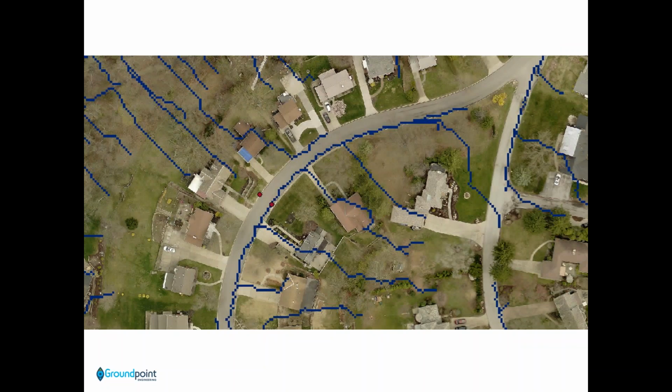Here are some more examples where you can see what the surface model indicates with this flow accumulation surface represented in blue, and where the catch basin inventory indicates where all the catch basins are. In some cases, the surface model shows that some catch basins are effectively getting little or no flow at all, where others are getting most or all of it. This could be a grading issue, could lead to an upsizing retrofit, or the need to add additional drains to the stormwater network.